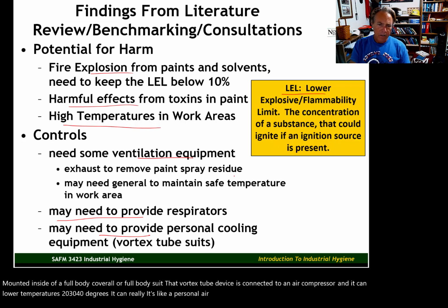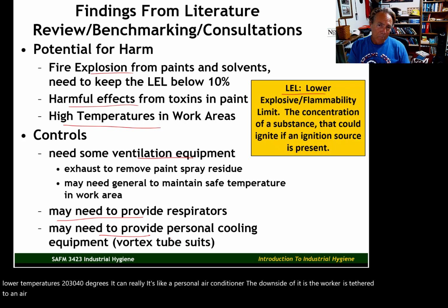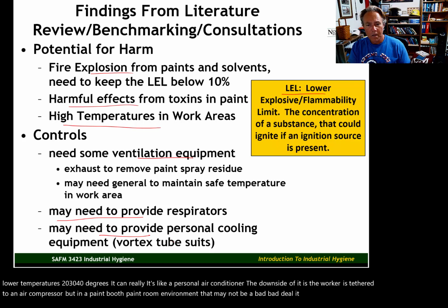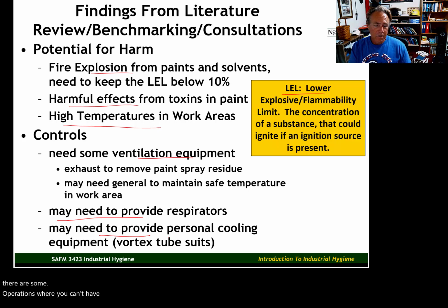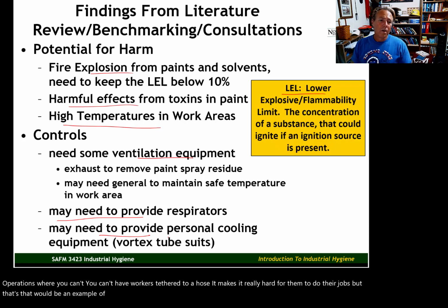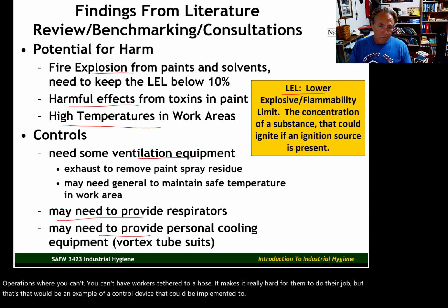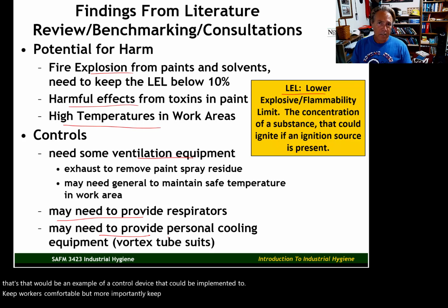The downside of it is the worker is tethered to an air compressor, but in a paint booth, paint room environment, that may not be a bad deal. It may be workable. There are some operations where you can't have workers tethered to a hose. It makes it really hard for them to do their jobs. But that would be an example of a control device that could be implemented to keep workers comfortable, but more importantly, keep them protected from developing a heat-related illness.